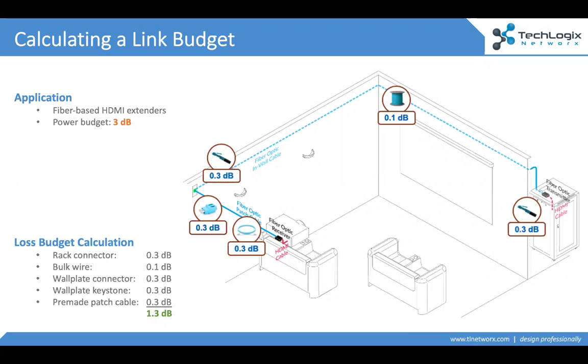It's when we get our equipment all installed, our cables and our wall plate keystones installed, everything's in the wall and connected, and we actually get out our tools and start to meter this run, that we can quantify: is our link budget proper? Is our loss budget within our tolerances? This is where tools become very important, because there are two sides to this. One, you've got to terminate and install cable and work with it. But the other part is you've got to be able to certify the performance, and make sure it's doing what it's supposed to do.